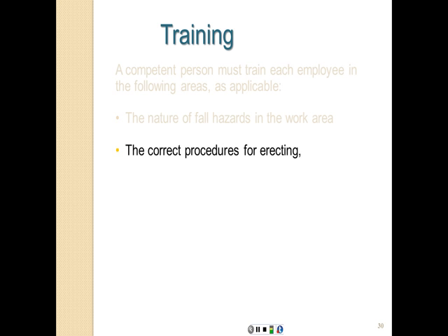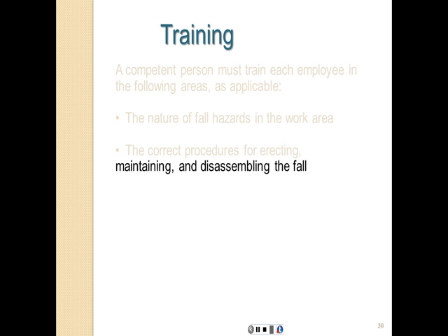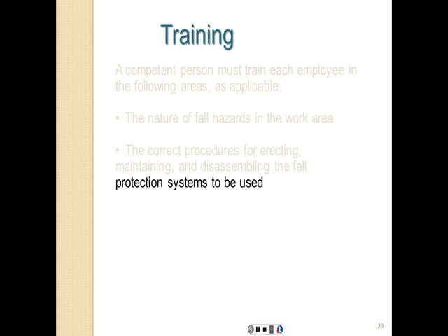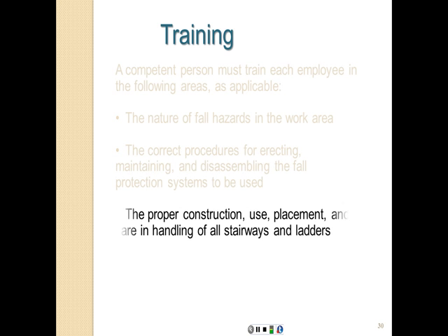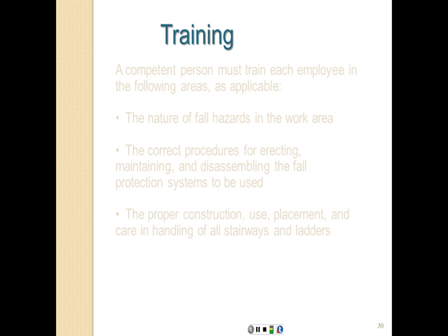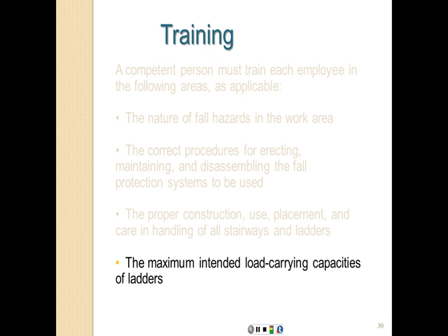The correct procedures for erecting the ladders, maintaining and disassembling them, and the fall protection systems to be used. The proper construction, use, placement, and care in handling of all stairways and ladders, and the maximum intended load carrying capacities of ladders, which again is going to be 4 times the weight of the person or the load that's going to be put on this ladder.